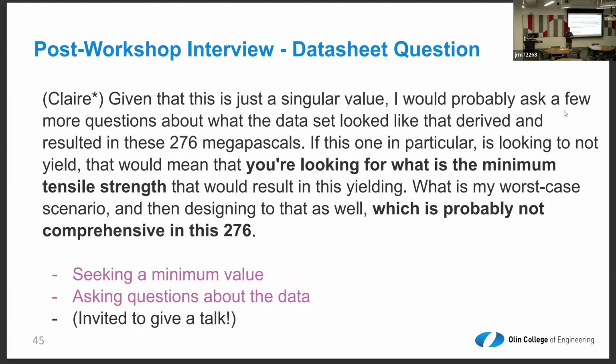But in civil engineering, one of the forms of code is called load and resistance factor design. Engineers end up using all these tables, and they reference these factors and use them in design. But actually, back in the 80s, a research team went through and quantified the variability that comes from materials, and the variability that comes from manufacturing, basically from job site to job site, say how the concrete is poured. They rolled all of that up into calibrating those factors so that they can actually achieve known reliability targets. So they know exactly where those factors came from, and they're very defensible. Quite a gulf between aerospace and structural engineering practice, though. I tried advocating for those sorts of things in aerospace. I was not successful.